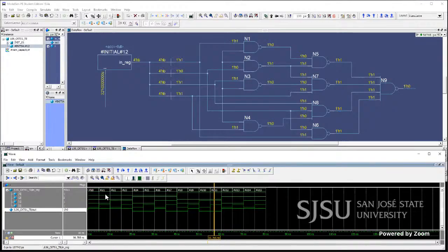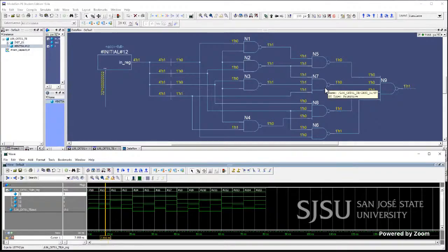And if you go to the timeline, let's say we are testing the representation of 1, you can see what logic values connect to which NAND instantiation in your circuit, and what data is flowing and crunching through the whole logic circuit to come up with the final result at the output.